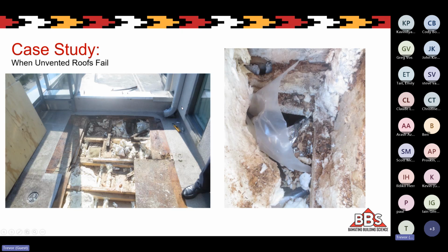As opened up, you can see, so here's the top of that parapet wall. And you can see the damage, especially the closer we got to the parapet wall, the more moisture damage there was. As we moved away, it was less. And so you can see this is the piece of poly that was supposed to be sealed to that block demising wall. It was just loose applied. And so you can imagine we got a lot of air leakage up into the system from that.